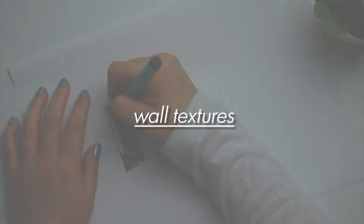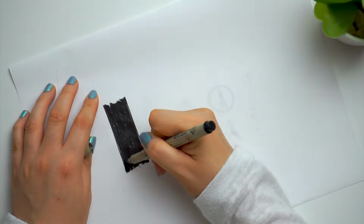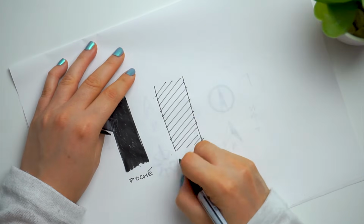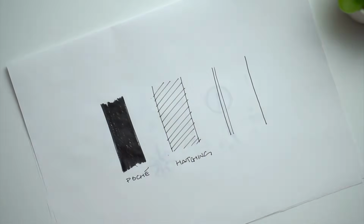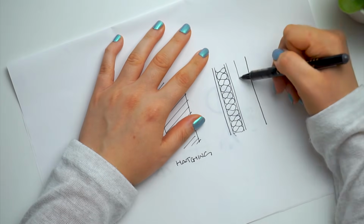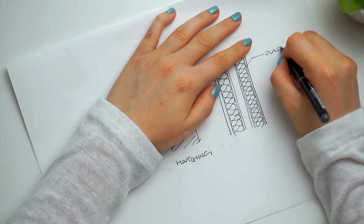The next thing I need to do is give the walls some dimension, and the way I'm going to do that is by hatching. You could also just colour the wall structure in black to give a distinct edge, which in architecture terminology is called poché. Sometimes people also like to simply draw the walls showing the texture layers as they would be in real life, and I use this method on my digital plan drawings actually. But my personal preference is to use a hatch to suggest what texture certain walls are.